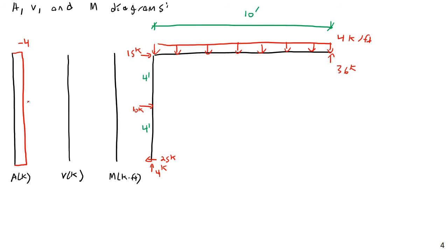So basically, you can have axial load diagrams just like you can have shear diagrams, and for columns where you have different vertical loads applied at different points in the column, it would actually be non-constant. For example, if I had a column that spanned between multiple stories, the load would be increasing as you went down the column. Actually in all columns, the load is going to be increasing as you go down, if nothing else from the self-weight of the column.